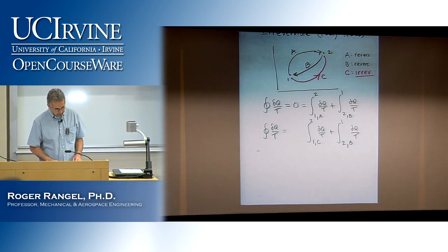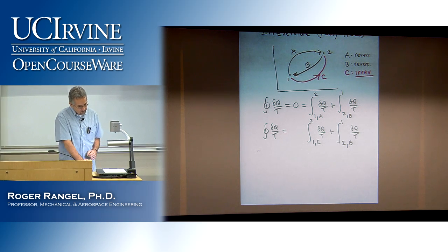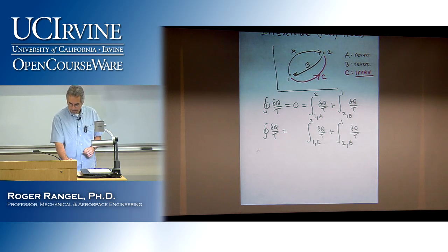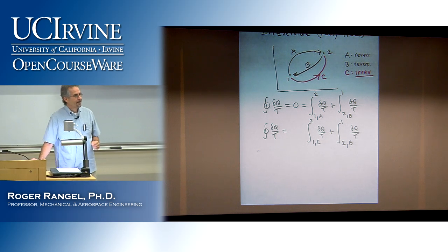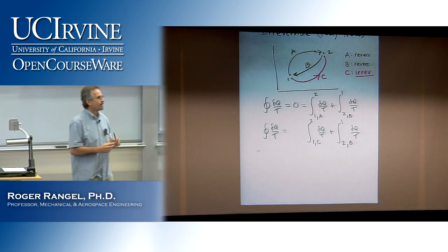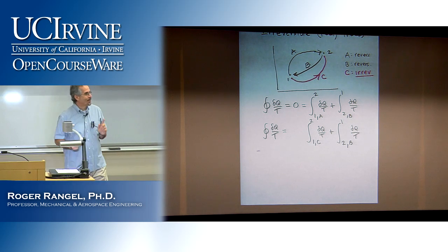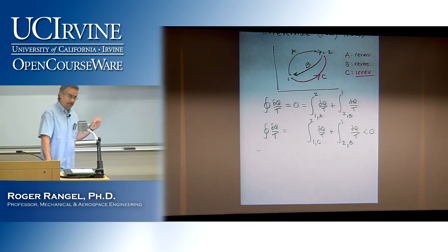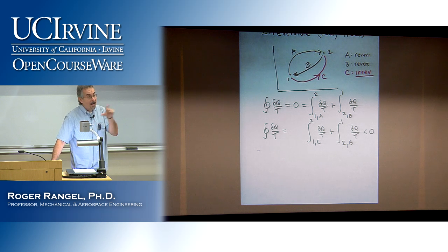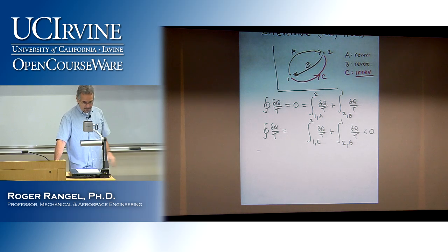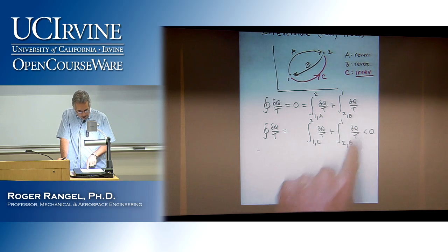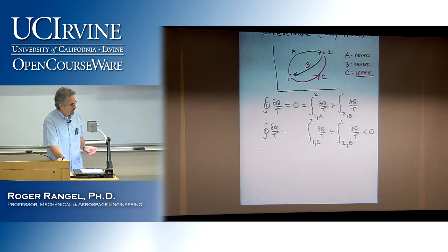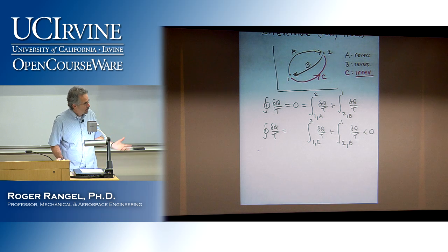All right? And what do we know about this one? What is this equal to? That's a tricky way to ask the question. It's less than 0. We don't know what it is equal to. We only know that this one has to be less than 0. Why? Clausius inequality, because there is an irreversible part that throws off the Clausius inequality to the irreversible side. So even though one of the two paths is reversible, the fact that there is an irreversible path makes the whole process irreversible. It just takes one portion to be irreversible to make the whole cycle irreversible.